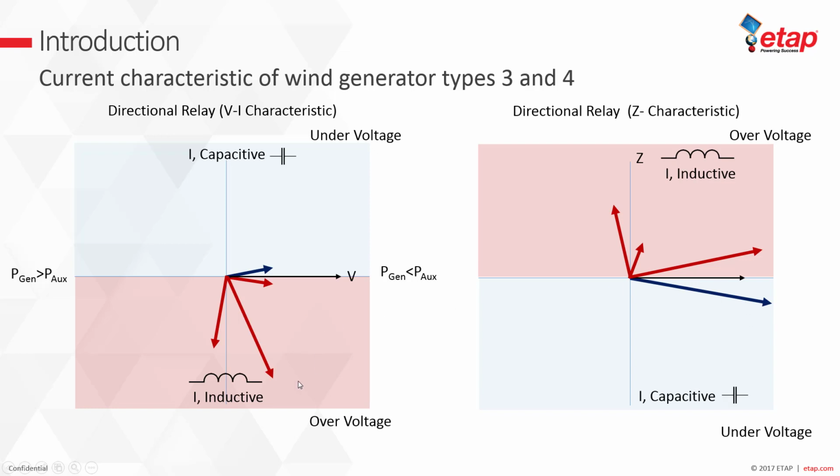If I have this current here, because current is a denominator, a higher current means a smaller impedance. So this current here represents this impedance on the right hand side. For this current here, a small current lagging a few degrees, when it is in the denominator, it becomes minus a few degrees in the numerator.